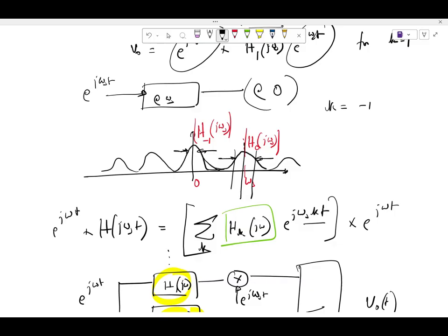So I can basically say that omega 3 dB is 1 upon NRC, right? And your omega naught is basically omega s. So your Q is omega s divided by 1 by NRC, times NRC, basically.